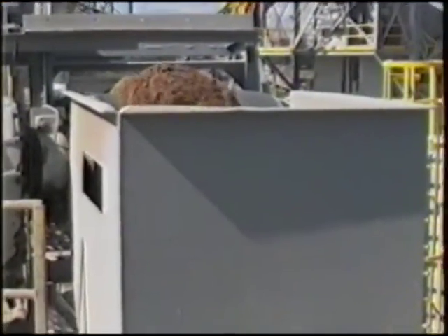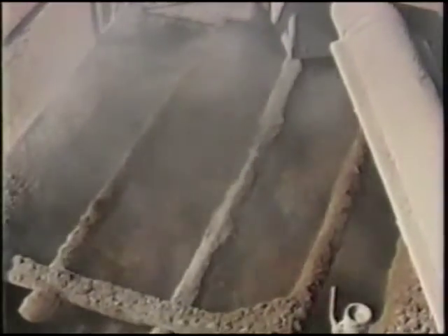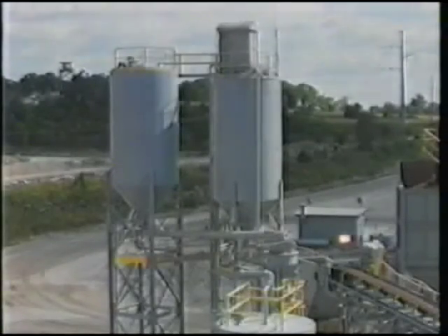Base materials are typically processed through a pug mill. A pug mill operation provides for consistent blending of the material, as well as provides the opportunity to add additional materials for proper gradation. Water can also be added to the base material through the pug mill to obtain optimum moisture for compaction purposes. At some pug mill operations, a cement silo is added to the system in order to produce cement-stabilized aggregate base material.